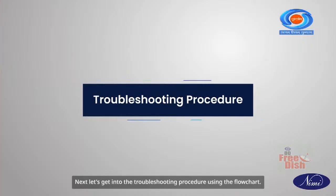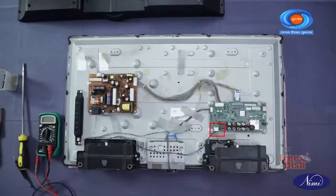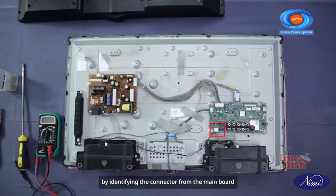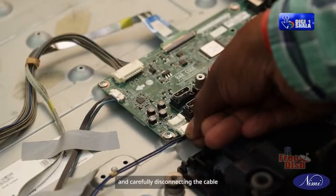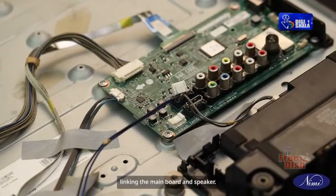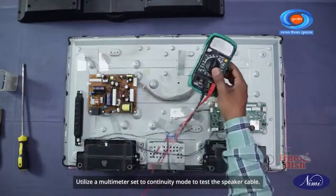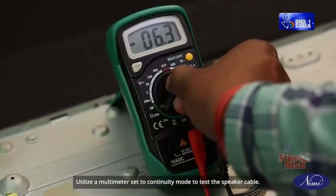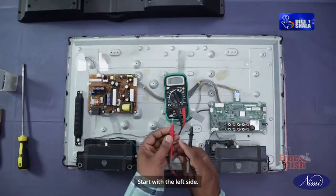Next, let's get into the troubleshooting procedure using the flowchart. To perform the cable and speaker test, refer to the provided flowchart. Begin the speaker cable test by identifying the connector from the mainboard and carefully disconnecting the cable linking the mainboard and speaker. Utilize a multimeter set to continuity mode to test the speaker cable. Start with the left side.